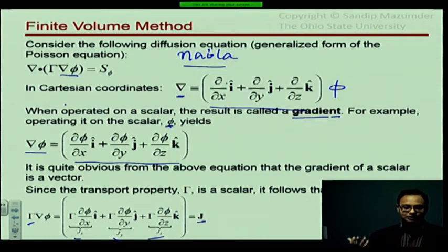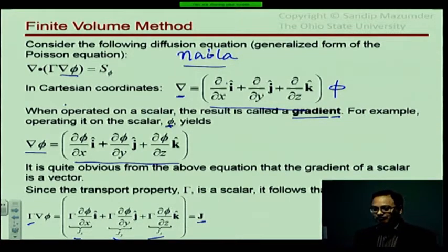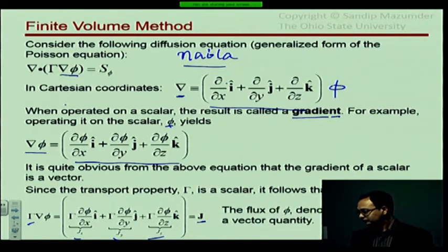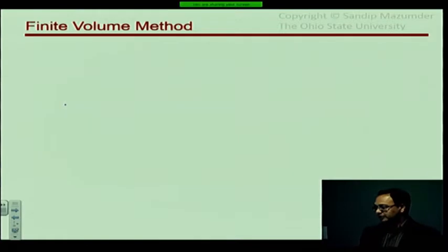So in undergraduate heat transfer, for example, you've been studying writing boundary conditions as k dT/dx is equal to h times (T minus T infinity). That's where that comes from. It's the flux that you're balancing. All right, so it's a vector quantity.